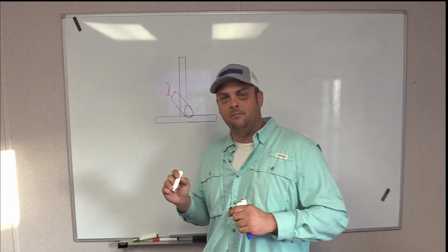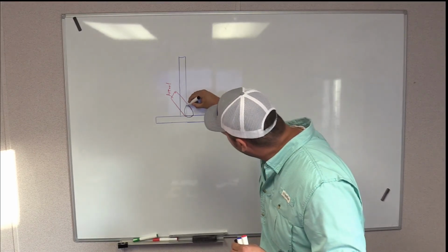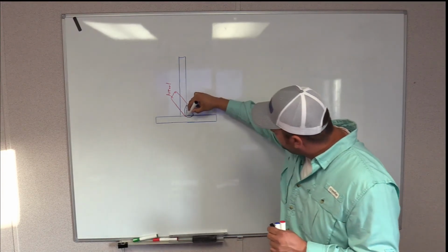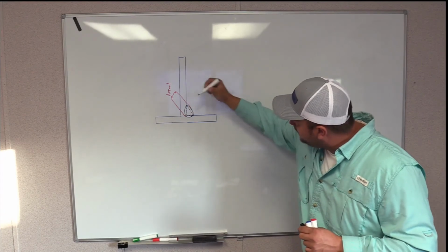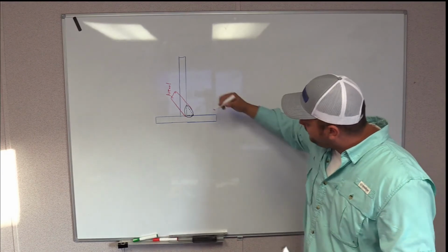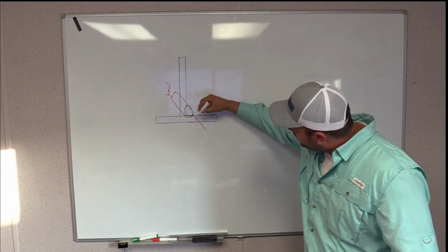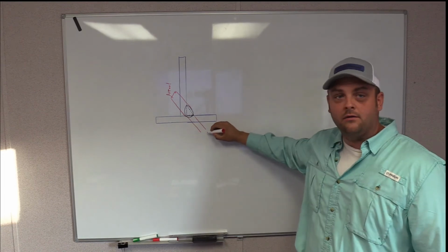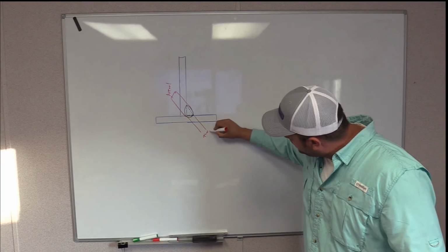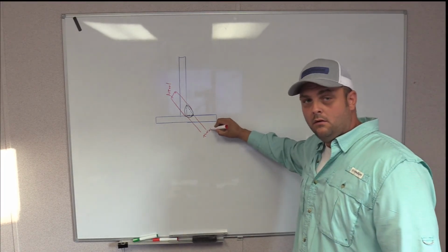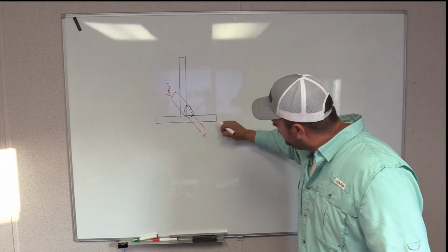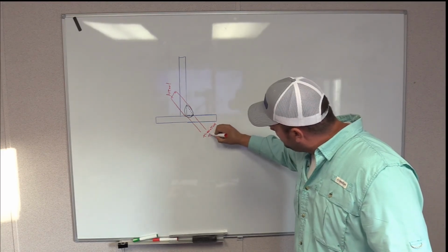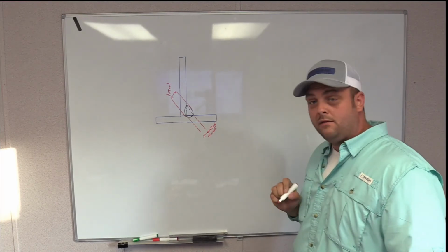And that's how this can be remembered, the perfect triangle that goes from here, down here, across here, from the face of this right here to the very point where these 2 pieces of metal come together. This is your theoretical throat.